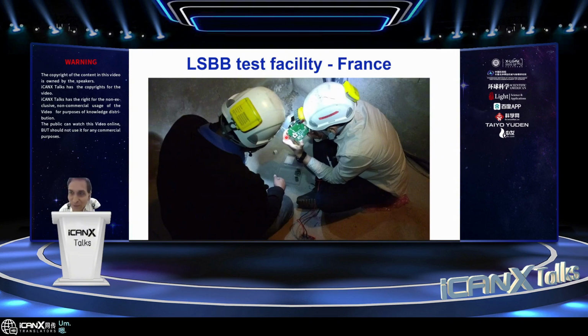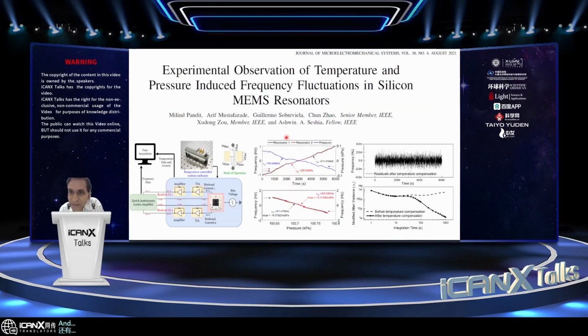But that whole week there and then subsequently at other facilities gave us a real insight into some of the limitations, because we were at least able to get rid of one of the ambient noise sources in the university environment. And it gave us insight into, for example, environmental effects that we published later on in JMEMS. So the impact of ambient fluctuations, environmental fluctuations, and their impact on the response of these devices.